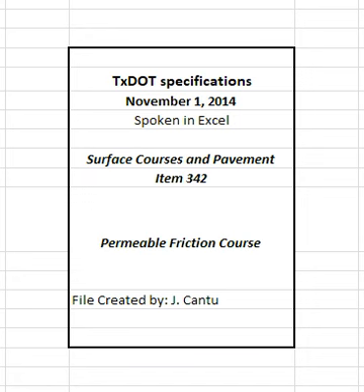The engineer will use the department's mix design template, when electing to verify conformance, to calculate the percent of Class A aggregate retained on the number 4 sieve by inputting the bin percentages shown from readouts in the control room at the time of production and stockpile gradations measured at the time of production.